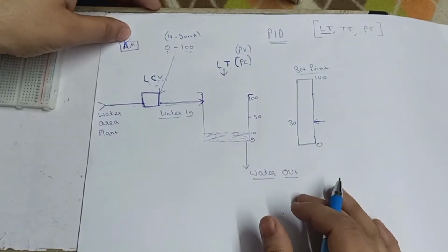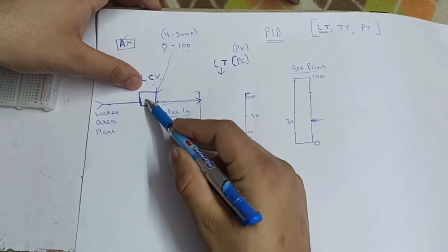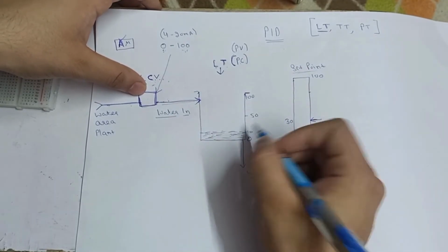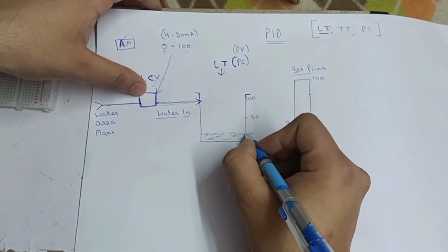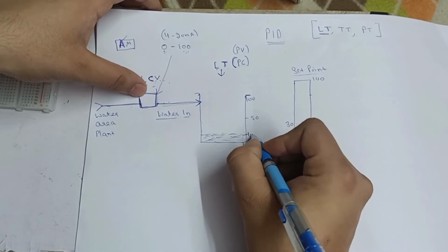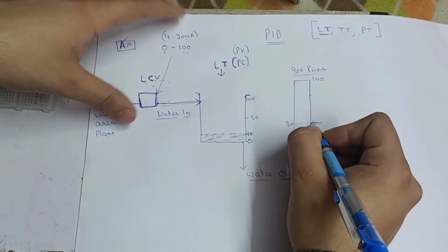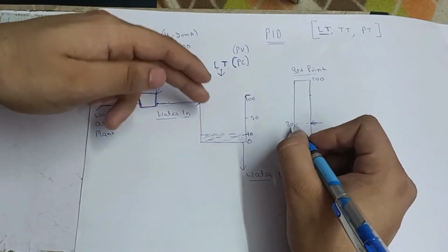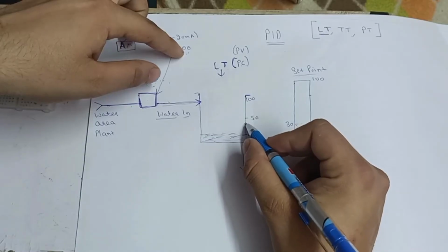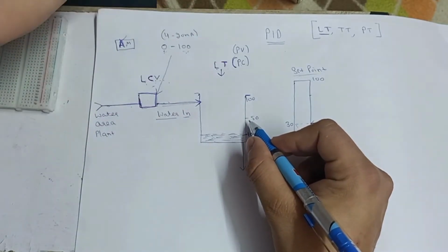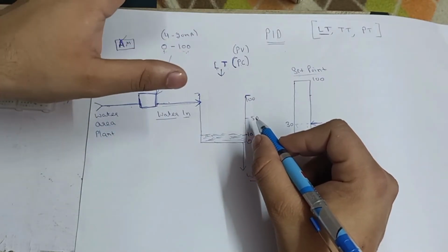When you click auto, the PID is processed and checks it. It opens the valve first and checks the condition. When I set the set point to 30, at the starting the tank is 10% filled. But we need only 30, which means I need to operate our tank process value at 30%, and it should stay nearby 30, not increasing more than 30% or less than 30%, with a plus or minus 5 or 10.